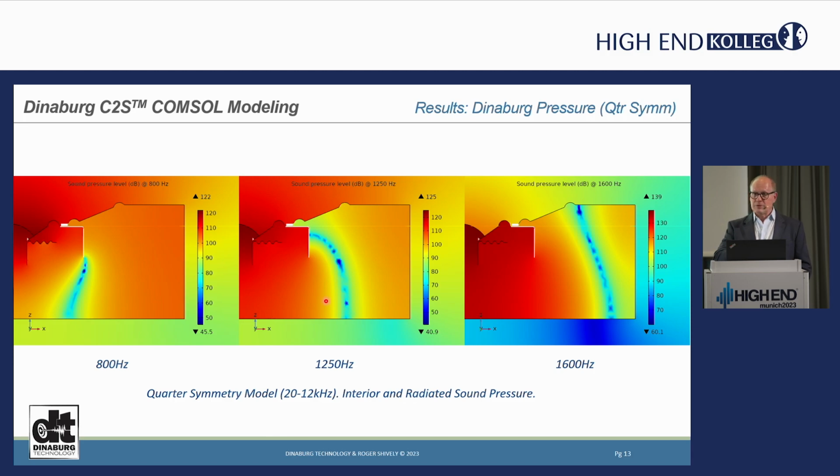interaction. So what happened when we took it away, I don't have the data here, but when we took away the phase ring, we started having less broadness of the off-axis behavior, so it started to improve. When you put the ring back in, you could see that it was actually changing the high frequencies, like in this range of from 1200 to 1600 hertz. It started to change the off-axis behavior. And it also changed the phase linearity, and it changed all the phase relationships inside the box. And it had a direct correlation to the listening experiences that we're having. So, yeah.